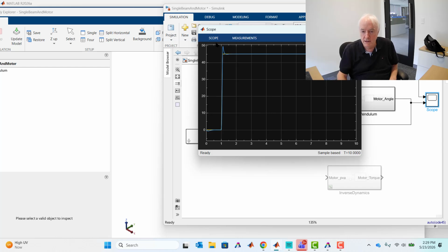All right. And basically, here's what your PID algorithm will give you. Right. And so it's because of that very strong, I'll call it gradient or whatever you want to call it, but really, rapid acceleration, it has a much bigger overshoot.